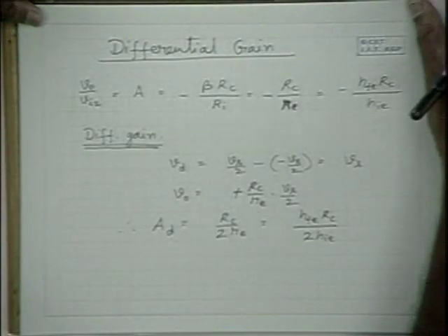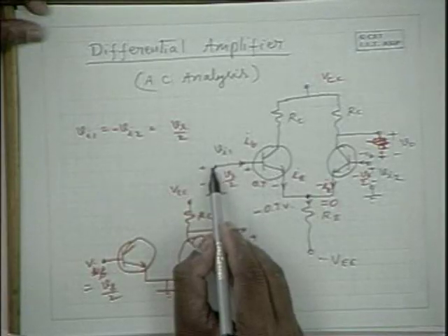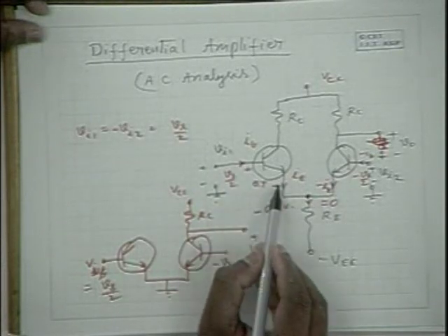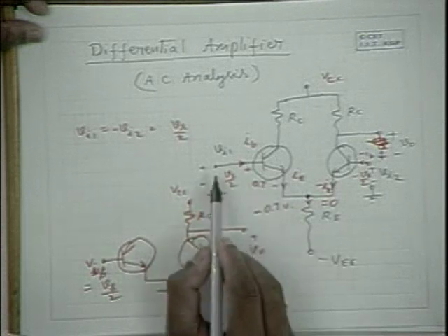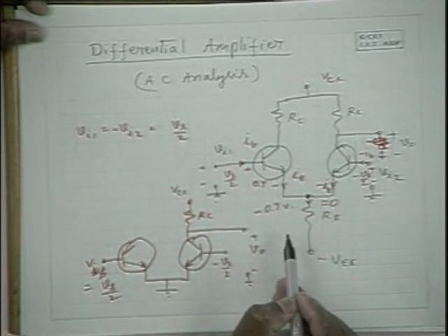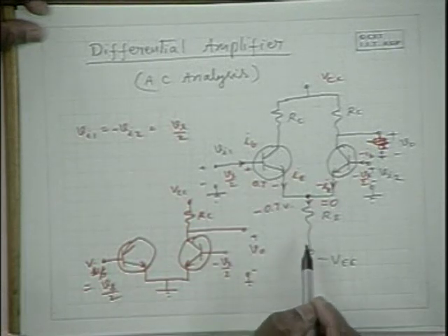In the circuit, the VB should be constant at 0.7 volts, but it is minus 0.7 and we apply VA there, sir. The difference. Yeah. Please note that here, in the absence of the signal, the input is grounded, and this is 0.7 volts. Therefore, with respect to base, emitter has to be about minus 0.7 volts. So that is the biasing voltage.